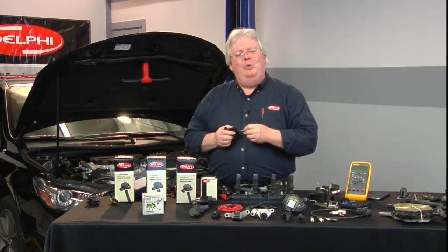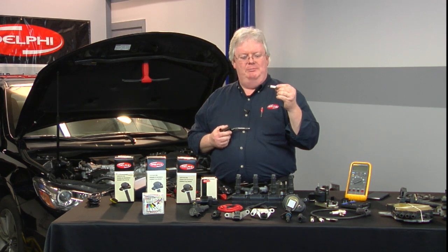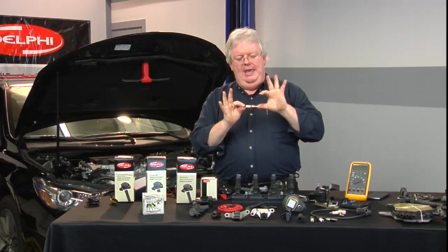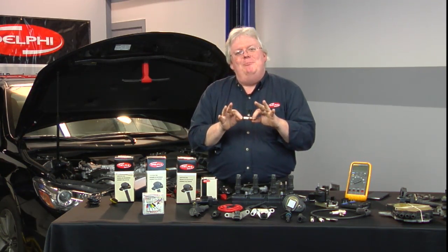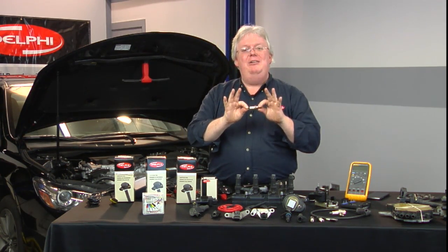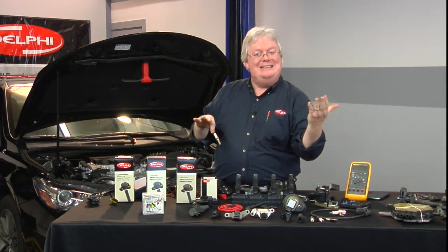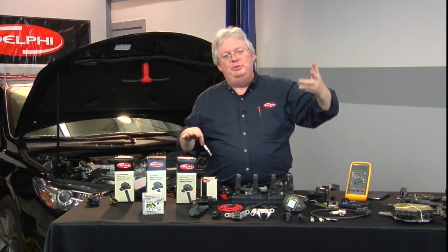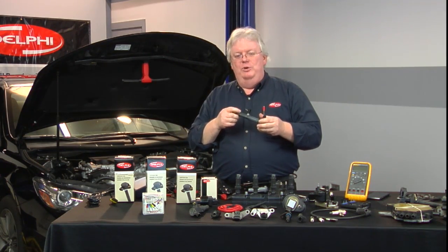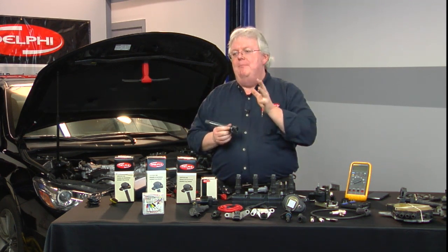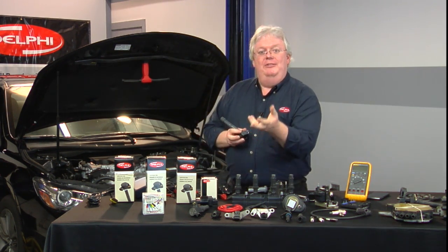But I've seen it in the Toyota manual checking out spark plugs themselves, going between here and here with the Fluke 1587, because Toyota uses that tool for their hybrids, and they're putting it on a good old-fashioned secondary circuit to see if it leaks. Basically looking at the resistance value, should be 2 gigaohms or whatever, unless it's leaking, then you'll see some number much lower than that. You could do that here on the secondary. It shouldn't hurt anything. That might be a way of flushing out that carbon tracing issue. Wonderful. We've got a question here.